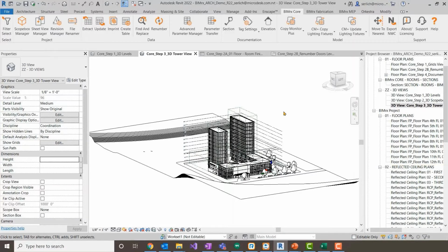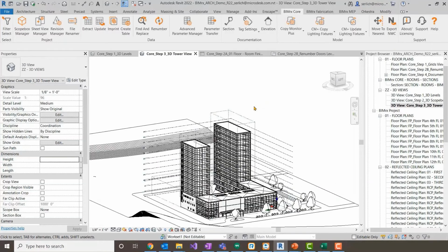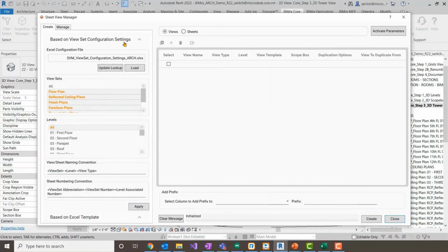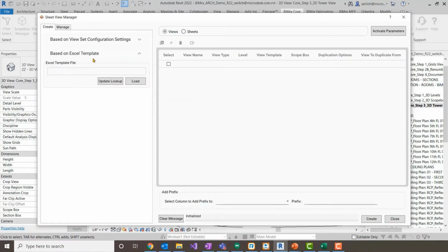You'll see here in my 3D view, I have the 2 towers associated to my buildings. So we might also want to create some dependent views of the different towers from our overall plans that were created earlier. I'm sure that duplicating as dependent your different sector plans is such a tedious task. We have to select each view, right-click to duplicate as dependent, repeat, repeat, repeat. Then we have to go back and rename all those views and then add all the scope boxes.